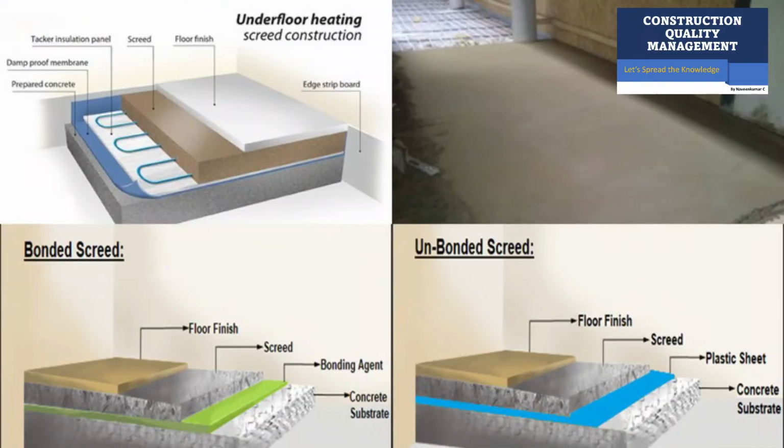There is another interesting type of screed that is called a floating screed. As the name indicates, it doesn't float, but it's a combination of cement, sand, mortar with a screed. Okay, normal concrete screed on the top. Generally, it accommodates services, especially in Western countries, or you can say northern countries, where extreme cold temperatures will be there, where we need to keep our floor warm.